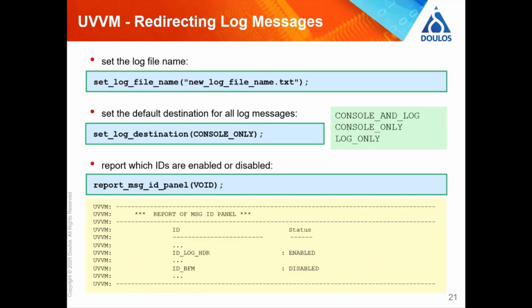This void is a curiosity of UVVM. For some reason, they're a bit allergic to the idea of having procedures that don't take arguments. So every time you get a procedure which doesn't need an argument, you pass it this special void thing.